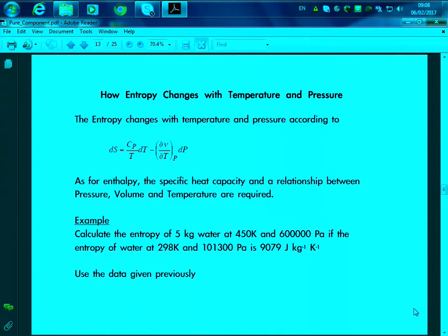So in order to mathematically describe this process, we need to use this equation. So the change of entropy will be, again, we will refer to the heat capacity coefficient at constant pressure, Cp, over temperature and changes in temperature, and again the changes in volume over the dP. And this will be the same equation as for enthalpy, but here we will have the temperature in the denominator. Okay? There's something else missing in this equation, and what we are missing is basically the phase change.